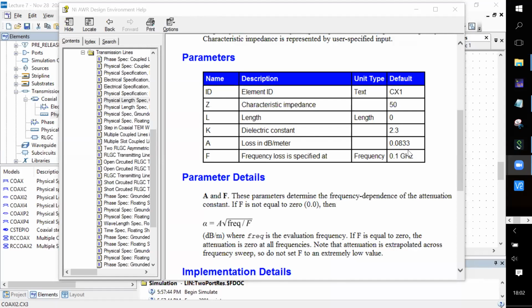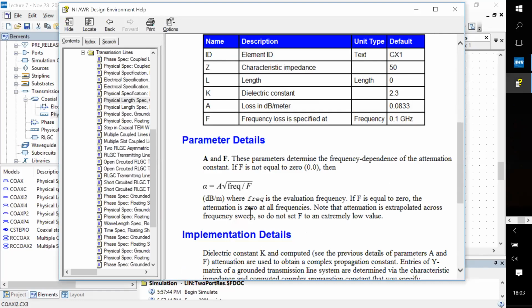Now, if you had looked at the section on the transmission line in Pozar, there's a part which discusses the weakly lossy transmission line also, that in the simplest case, when you have a very small amount of loss, you have this exponential decay of the waveform. So from that, you can actually calculate some loss here. And by default, there is a frequency dependence to the loss, because that is how typically most materials are. But for our purpose, we will not worry about it.